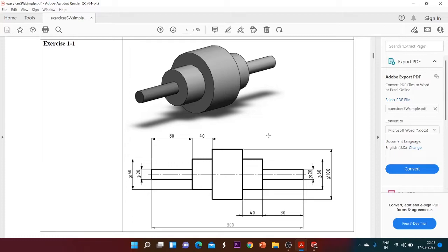of any component, and then we can revolve that quarter section 360 degrees about a center line or an axis line to get that revolved part. The first condition to have a revolve part is that the component or sketch should be symmetrical around the revolving axis. So here you can see a component which has to be revolved by us. It is symmetric about the central line, or you can say the horizontal line of our component.